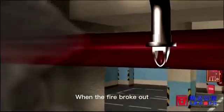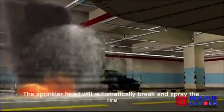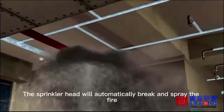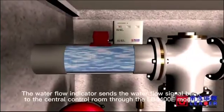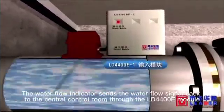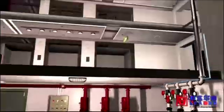When the fire breaks out, the temperature rises to the rated value. The sprinkler head will automatically break and spray on the fire. The water flow indicator sends the water flow signal back to the central control room through the LD4400E module.